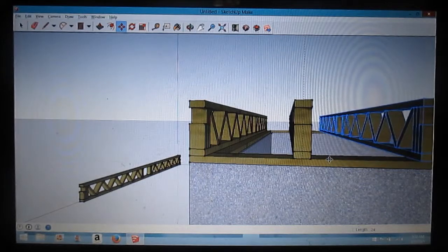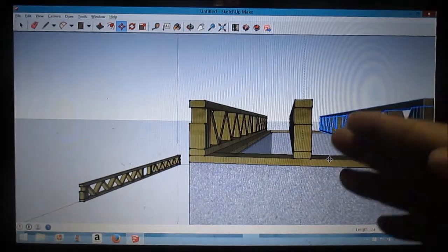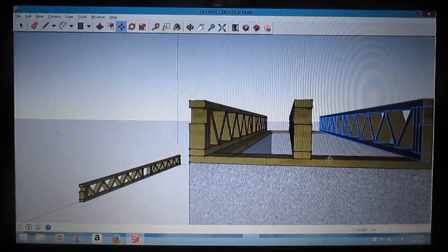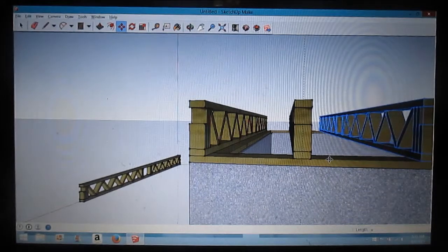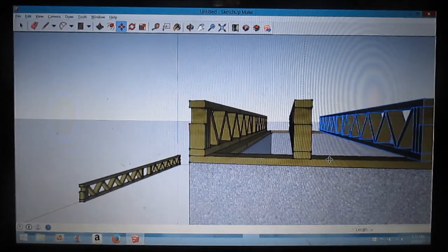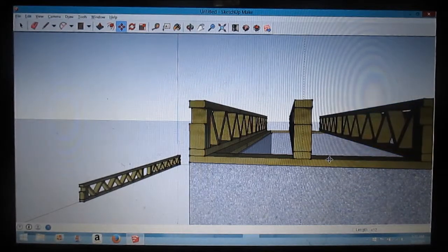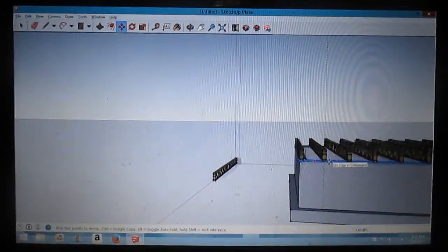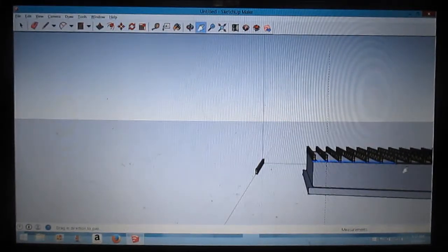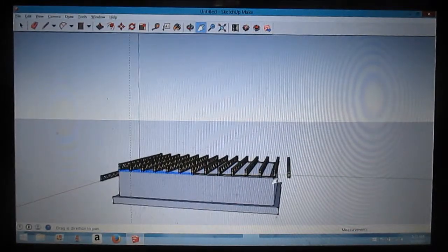Now I'm going to make copies of that. I want to make several copies, so now I'm going to hit the X button. That means times how many times I want to copy that in that same pattern. So I'm going to do 12, X12. Then I hit enter. And that should have made copies, which it did. See, that's a cool little trick. Oh, made too many.